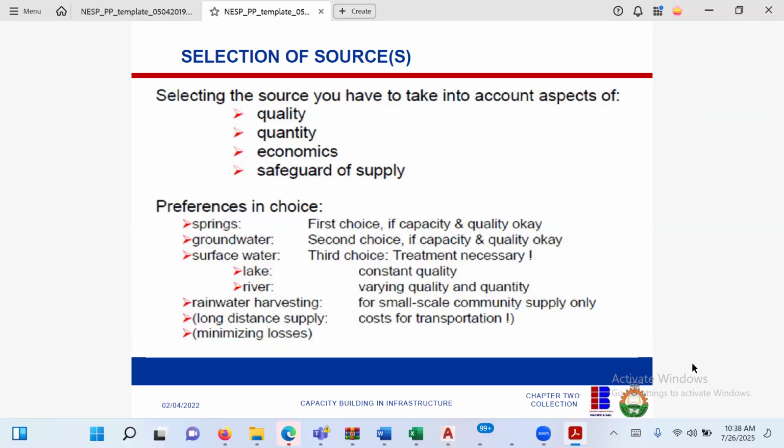Okay, and that comes to pumping testing, do your drawdown, so that you know, and it also helps you to know what kind of pump to use, so that your level of extraction does not undermine the recharge. Then the next factor to consider is the economics. What is the economic of getting this water?